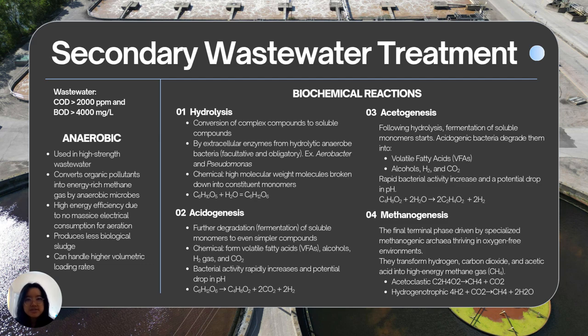Now, let's talk about the secondary wastewater treatment. From the case, the wastewater has a COD of more than 2000 ppm and a BOD of more than 4000 mg per liter. Since this wastewater can be considered high strength wastewater, anaerobic treatment is preferable to the aerobic one.